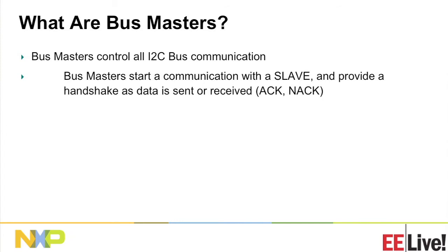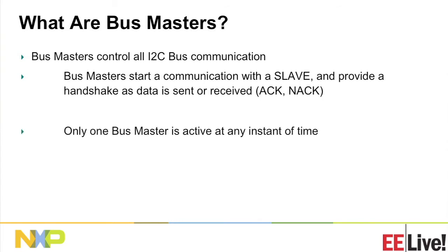So a very simple beginner mistake is, I connected my microcontroller GPIO to the bus and it doesn't work. And the reason might be that you use the tri-state or pull-up device on your microcontroller instead of an open drain, or open collector, well, I doubt you'd get open collector on your microcontroller, but an open drain device. So if you're debugging hardware for the first time, one of the first things you might want to look for is whether the microcontroller has a tri-state or an open collector output device.